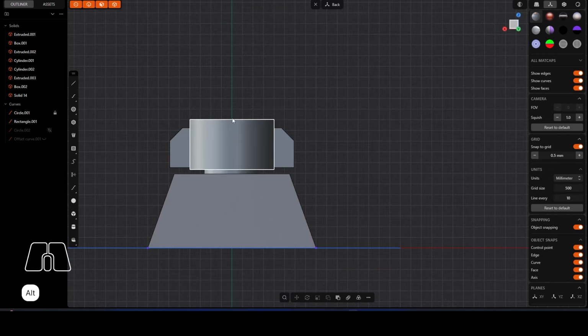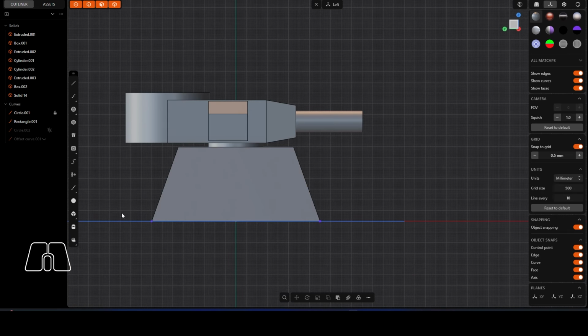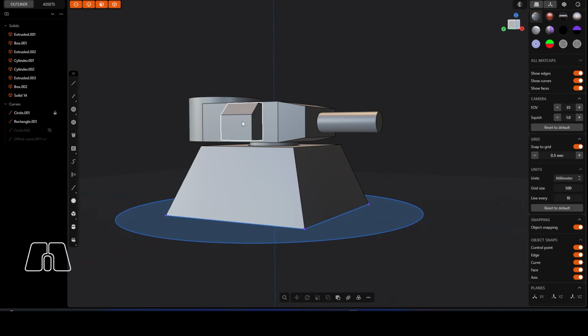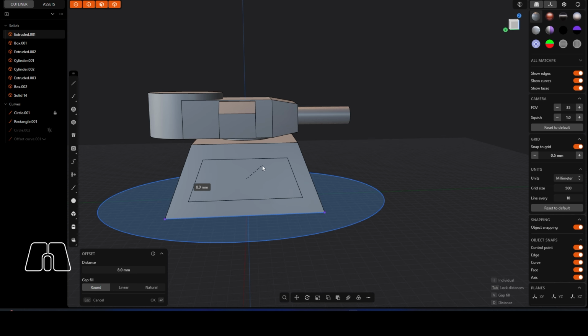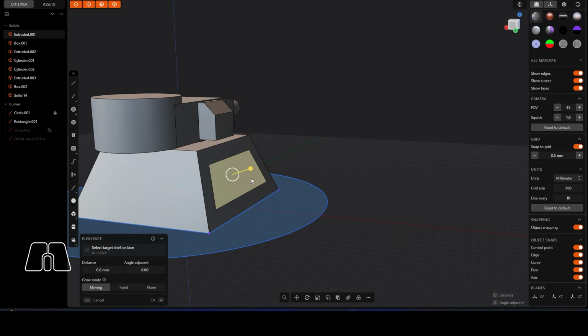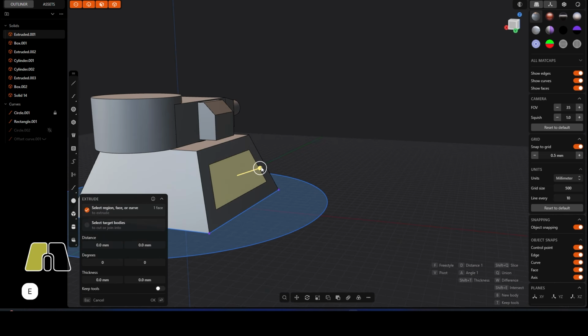So I think in terms of its silhouette, there's a bit more work to do. Definitely on the bottom bit here, we need to add some more features as well, similar to what we've got at the top here. So what we might want to do here is use the Alt key, and we can bring maybe something out like this. We can do an extrusion from here. Now the problem is it's going to extrude from the angle.